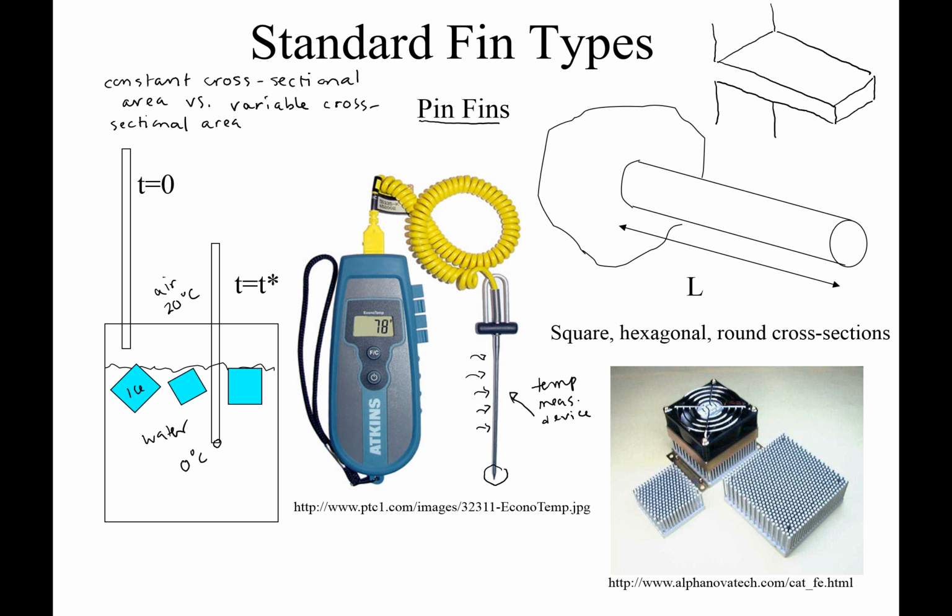This is your measurement location, but that measurement location might be affected by axial conduction. So you have 20 degrees C air here, and there's a heat transfer coefficient to this T infinity, which is air, and then you have a heat transfer coefficient in the water and this temperature of the water. So to understand this problem requires an understanding of fin type analysis.